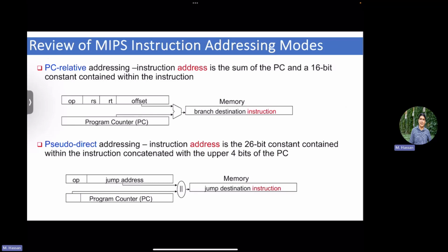During the break, one of you was discussing with me what would happen in a CISC x86 branch condition. I have variable instruction length. How do I jump? Well, I have variable immediate values. How do I add? It's a very complex logic to determine how you resolve branches in x86, right? So why in RISC is it very simple? Because everything is fixed, limited. There is no variability or uncertainty in your math.